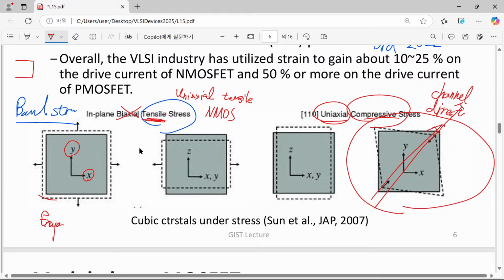This is just a nanometer scale, several nanometer or micrometer scale chip. However, at a certain position, we apply compressive stress, and at a certain position, we apply tensile stress. So this is actually the magic by our fabrication engineers. Therefore, we can locally introduce local stress to individual MOSFETs, so they can be improved.